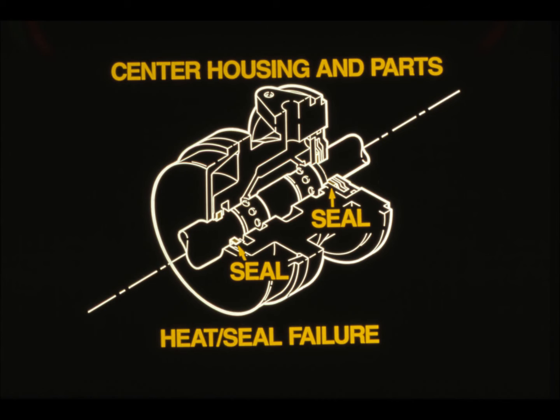Seal failures in the center housing are often secondary in nature. Seals can take a set and fail when exposed to excessive temperatures. Bearing wear and shaft movement also create seal problems.